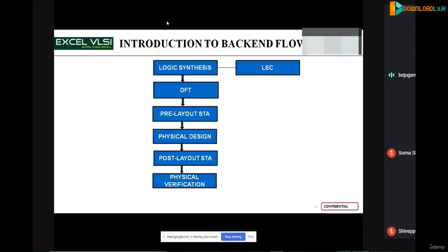So once this interconnectivity timing analysis is done, we'll enter into the physical verification stage, where we perform the checks related to physical design, and what those checks are, we'll be seeing in the later slides. So once we do the timing analysis, we need to check the physical connectivity, how the physical implementation has been done. Whatever checks we perform once physical design is done is called physical verification.